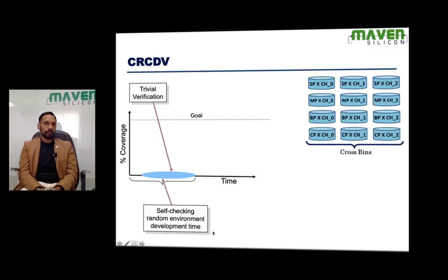It's a detailed process. Basically, we write the source code for every component: generator, driver, monitor, scoreboard. There will be different kinds of components, and we connect all of them with the help of a mailbox. Once we put all the components in the environment, it's not going to work as you expect because the environment is going to be complex. Try to recollect the router example which we discussed: multiple drivers, multiple monitors, too many connections. So the environment is not going to work as you expect. It's not going to happen easily, so we need to bring up the environment.